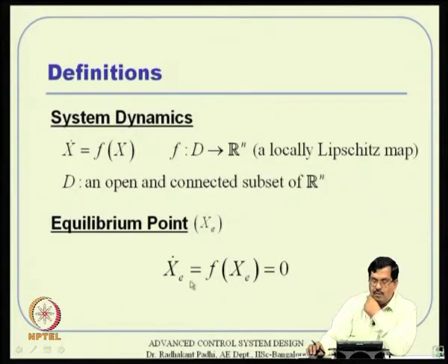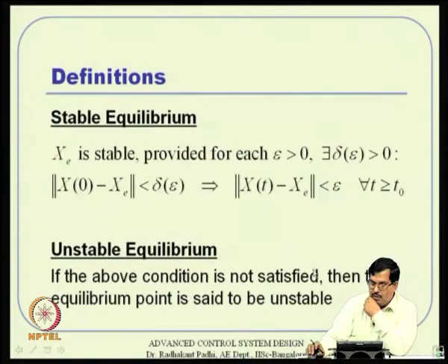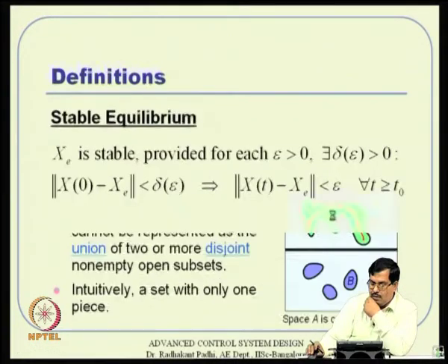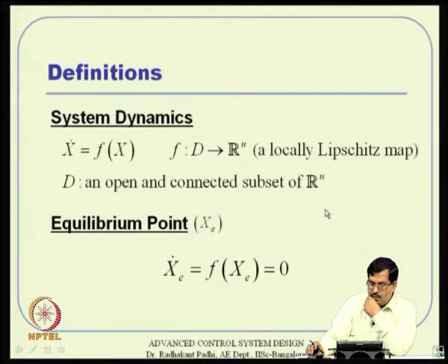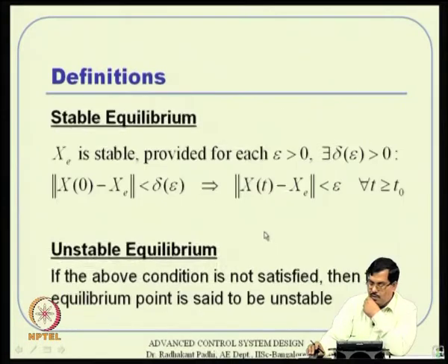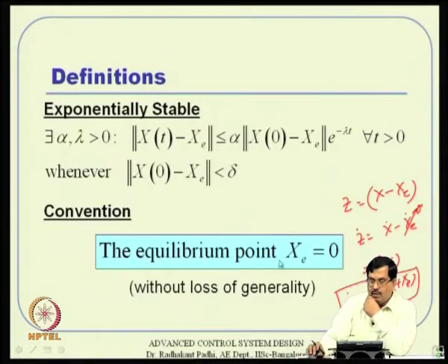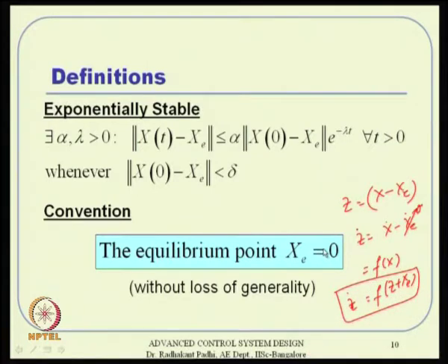We studied further. x e turns out to be an equilibrium point, but with change of variable, we will be able to tell that x e is 0. I mean with change of variable that we discussed here, then further theorems with x e is 0. So, if the original system equilibrium point is non-zero, then you have to do this coordinate transformation first and then interpret the system in terms of variable z, then proceed further to show the Lyapunov theorems.